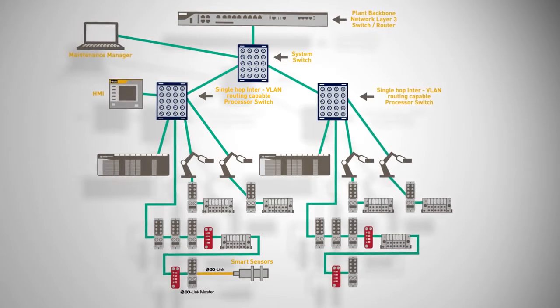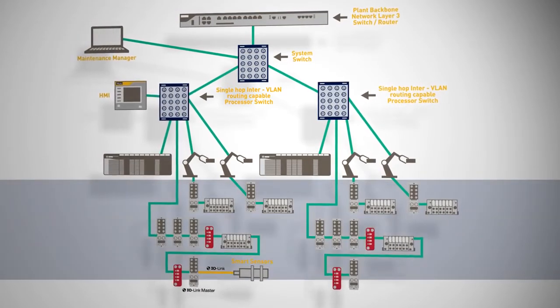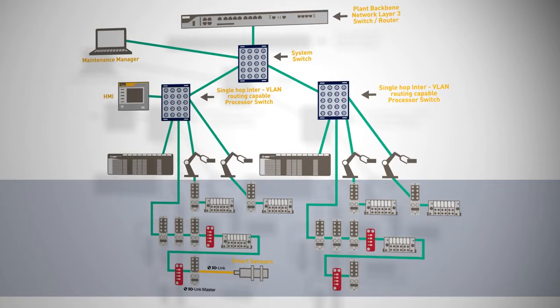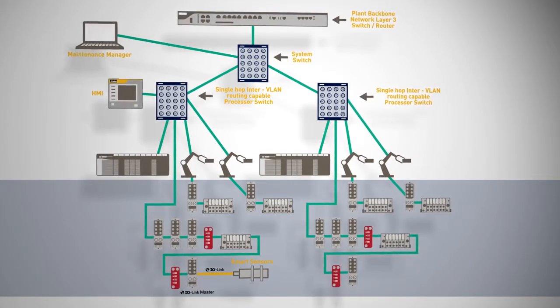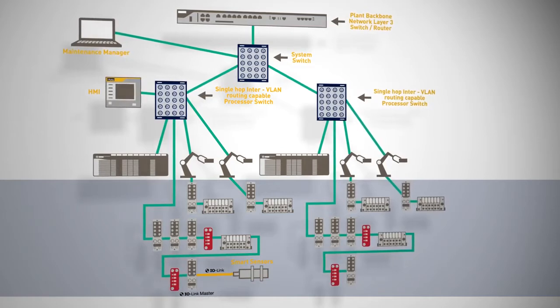Where we really see I/O link looking to be expanded is in that lower section. That I/O section is where we see the cost of the I/O architecture being greatly reduced by the expansion of I/O link. So if we look at the global trend through the IIoT history, or where we think smart factory really is going, is you have the development of smarter sensors.